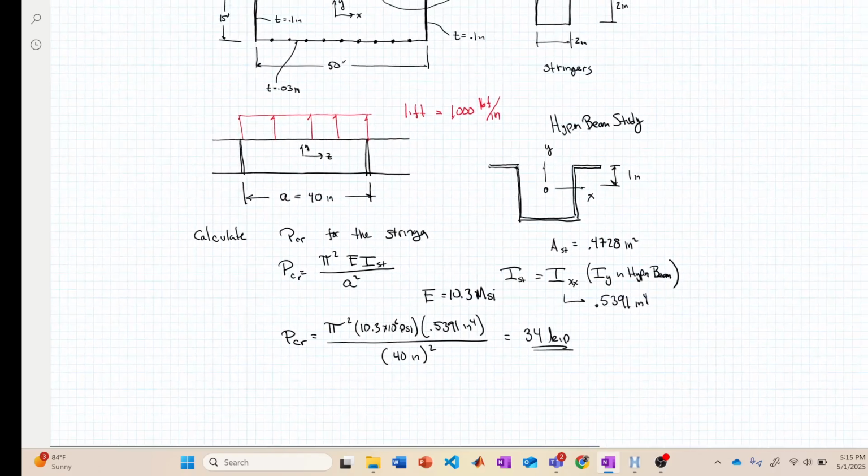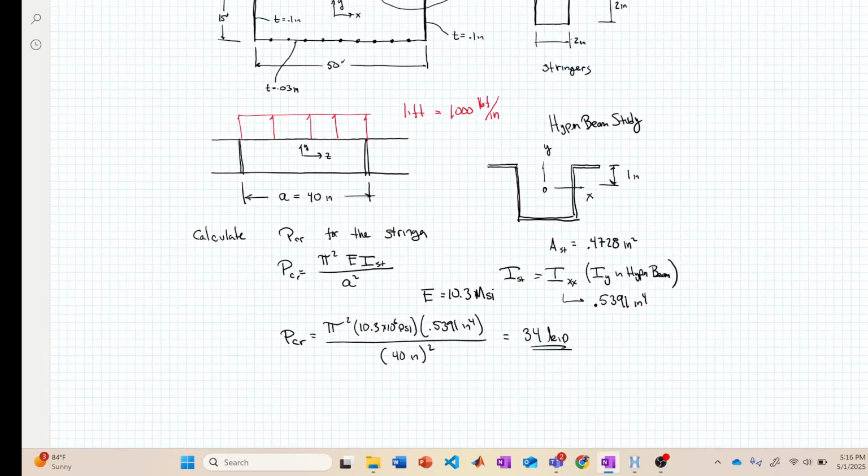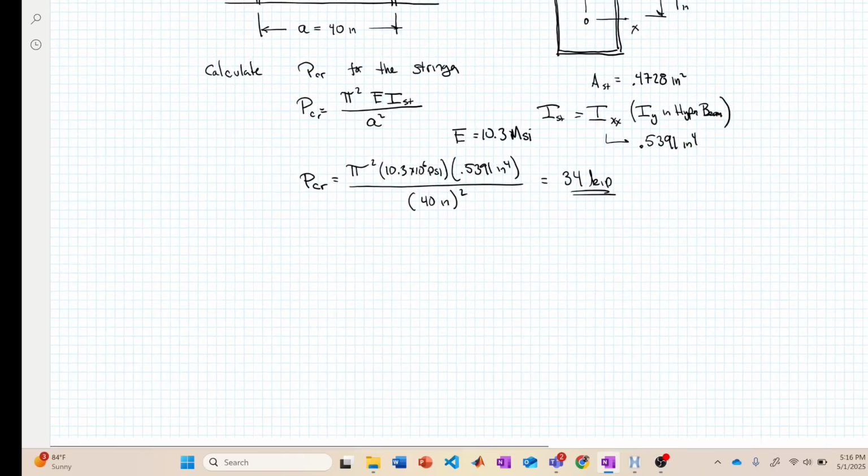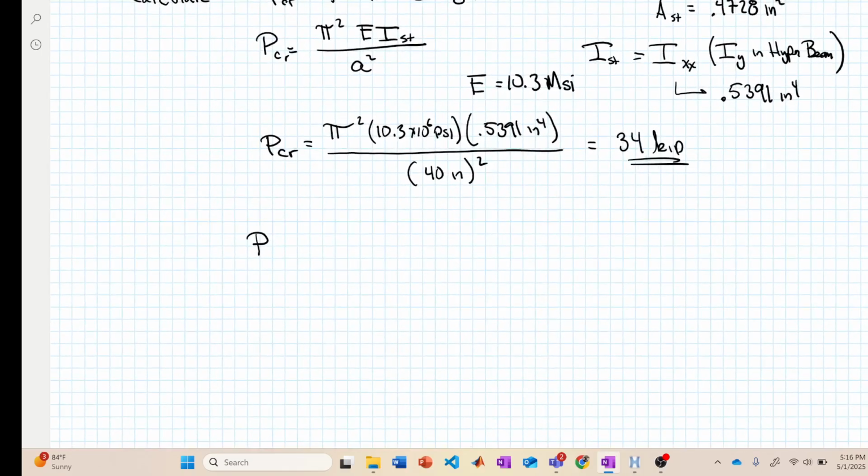Okay, well, we need to figure that out, right? And so, this is not given to you directly. You have to calculate it from the lift loads. All right. So remember, to get this, the actual force in the stringer is going to be, again, that change in the bending moment over the spacing of that rib section times Q. Now, this is going to be Q of the stringer over the I of the entire cross section.